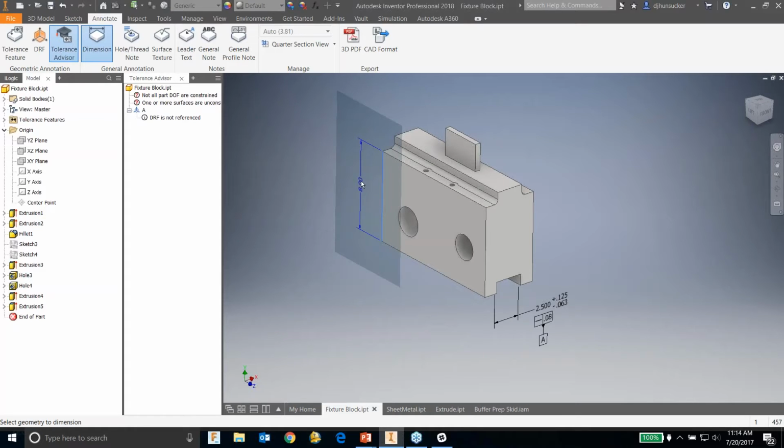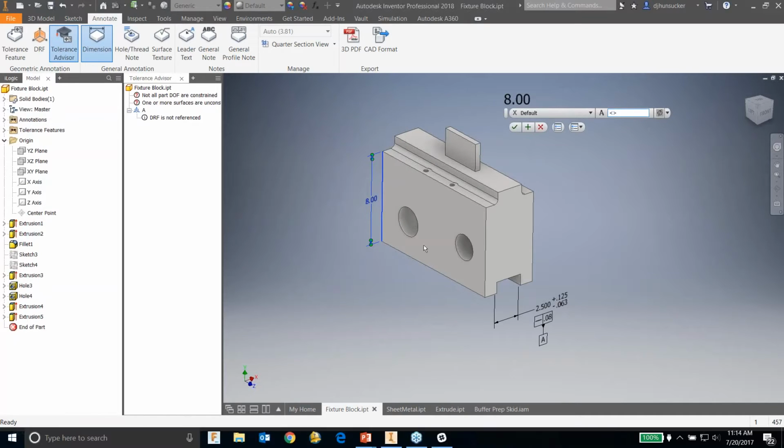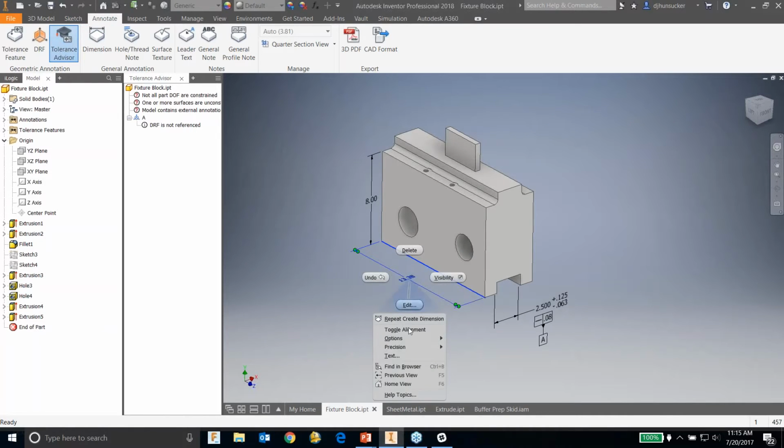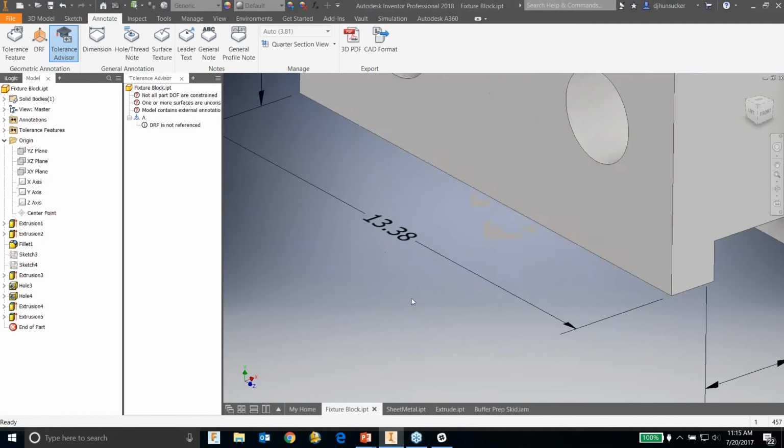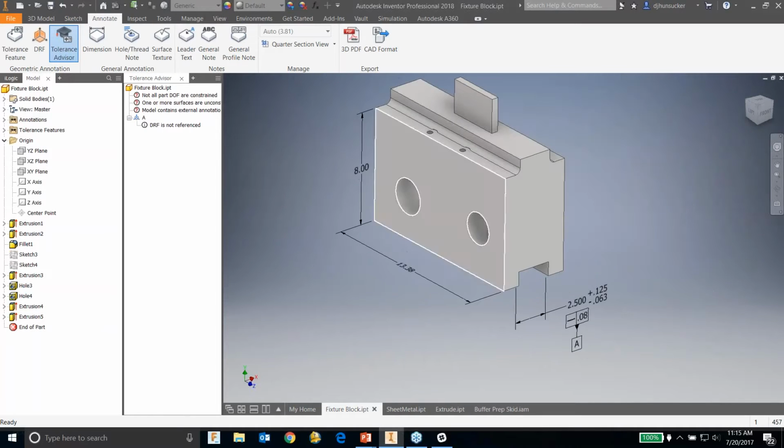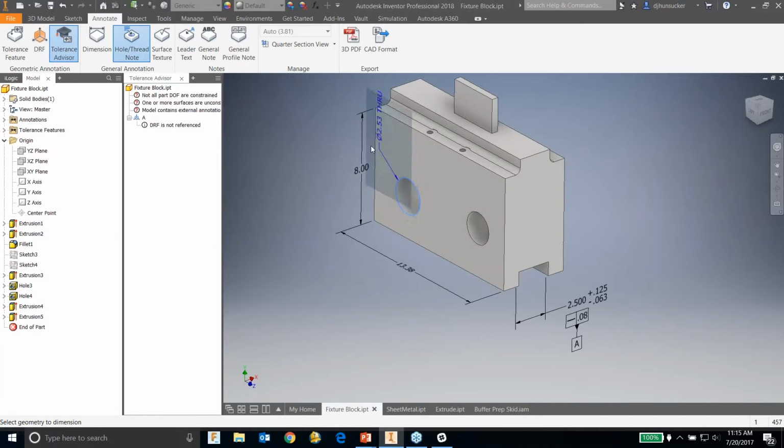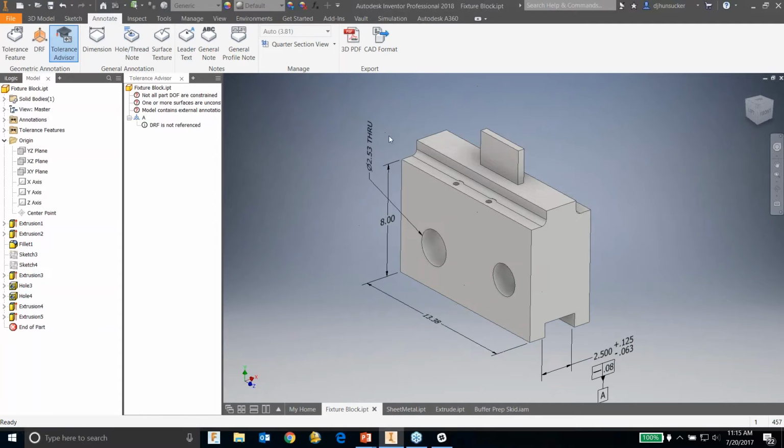And if you're used to dimensioning or isometrics in the drawing, spacebar is still your toggle to toggle what plane it's on. So I could actually add those dimensions. I'll drop them in there and so forth. So that way you can also toggle the alignment, if I wanted to shift in a certain direction. But then also drop a hole note in here, and same, I might toggle that. There you go. So that way we can kind of detail this.